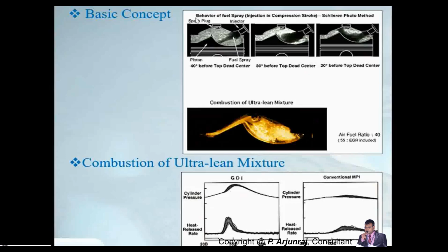We will see the behavior of a fuel spray basically in a compression stroke. This is one of the methods that is being taken. So here, based on this pattern, they have derived the crank angle versus pressure or heat release graph. This is the graph basically.